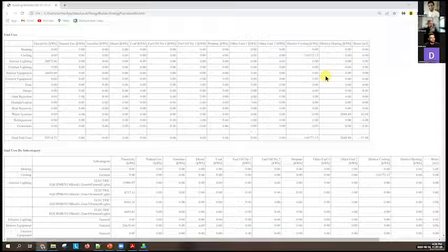And these are thermal energy numbers, because when we do an ideal system or a simple system in EnergyPlus, it doesn't really model compressors and fans and pumps and so on. It just tells you what is the heat load that needs to be extracted or added to that space to keep that building or that space comfortable.